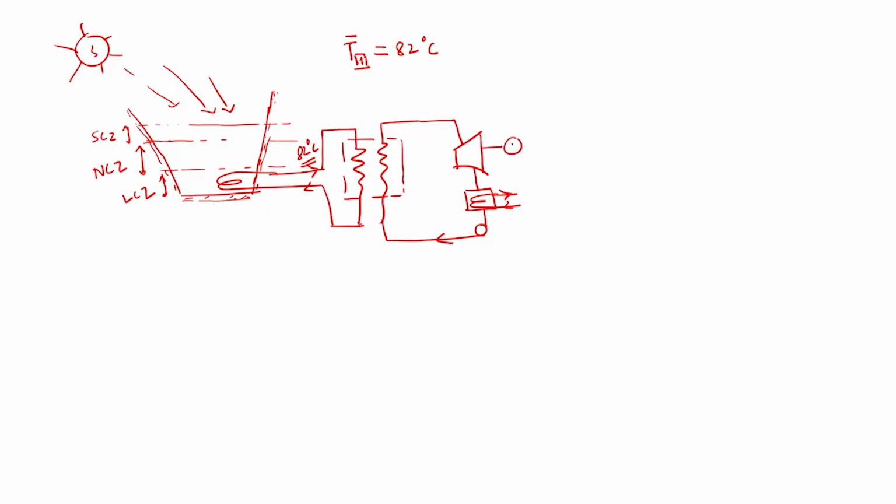So, what we will get, this is 18 kilowatt. Okay. So, this is turbine, this is condenser, this is pump WP. So, pump work is neglected here, and this is the heat exchanger. So, this hot water goes in the heat exchanger and exchanges heat with this organic fluid, and then fluid will be evaporated or refrigerant will be evaporated like ammonia, what we have used in this setup, or maybe other refrigerant R22 can also be used.